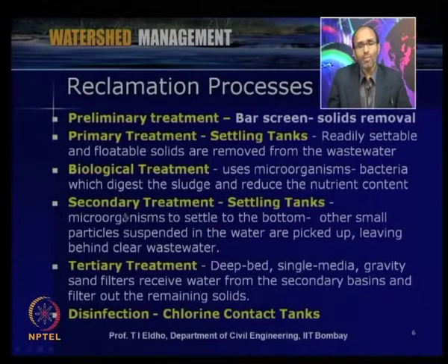And then if you want a more purified form of reclaimed water, we have to go for the various tertiary treatments which we discussed in the last lecture, like deep bed, single media, gravity sand filters, which receive water from the secondary basins and filter out the remaining solids. Then we can send the reclaimed water through filters like ultrafiltration, nanofiltration, or reverse osmosis, so that the most purified form of the reclaimed water is obtained.